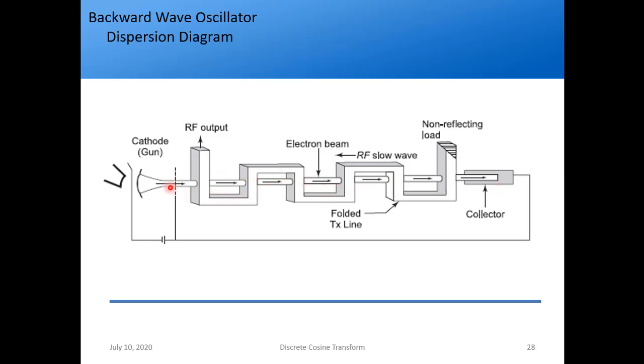So what is happening? The electron beam is going through this path. The holes are cut through this structure here. Corresponding to this, the RF signal will be generated due to noise, again due to this DC noise, right? Again there is no input here. That RF signal will induce electric fields here, so they will again oscillate from left to right and right to left. So again there will be velocity modulation, right?